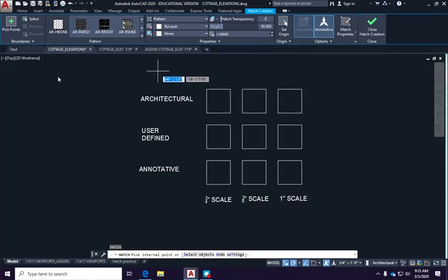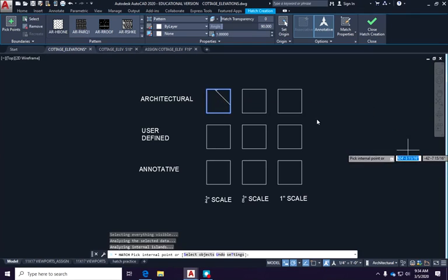And now I have it selected, and now he wants me to pick inside a point. When you hatch, you have to hatch inside a boundary. You cannot hatch because if you remember, our black background is deep space. It goes on and on and on forever. And your computer will blow its mind if you tell it to hatch way off into deep space. It needs a border, which is why we drew this little rectangle or this square. And I do not know why I'm just getting that, but I'm just going to click for fun.